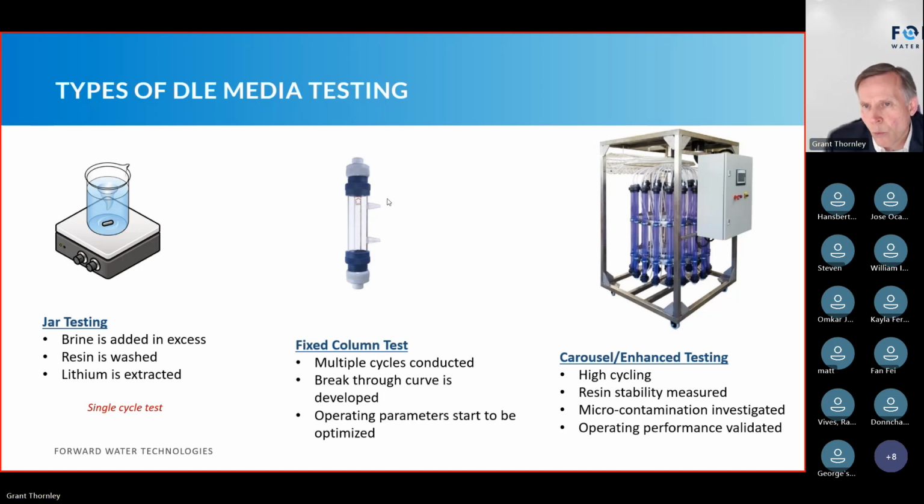Why I pointed that out: if you see, this is a jacketed column. People have wrapped tin foil around it, trying to jacket it. This is a very effective way: if I use a heated oil or glycol solution, I'm going to flow that around the column, and I'm going to be able to maintain and control my temperature very precisely while I operate this. I don't want fluctuations in my temperature or variables. So if the client doesn't have it, or you don't have it, I would highly suggest getting that.